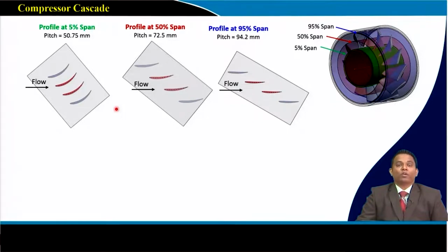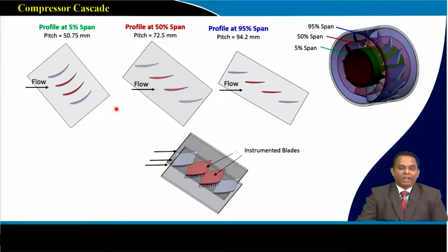Okay, so in order to select the aerofoil at a particular station, we need to have data. The data we are looking for is my CP. CP represents the pressurizing capacity of a particular aerofoil when we are talking about application to an axial flow compressor. So we will arrange our blades in this manner. Here, if you look, these are two blades, called instrumented blades.